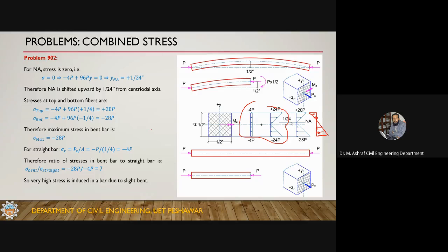Now if you have a vertical column, okay, and let's suppose practically, usually the column size is like 12 inches, 15 inches, 18 inches, 24 inches. These are the usual sizes of column, and the height is usually from 10 to 12 feet. Okay, and if you have a column of 12 inches, and there is an eccentricity, a bend in the column equal to 12 inches, which is practically not so much possible. Practically, the eccentricities are not so high.